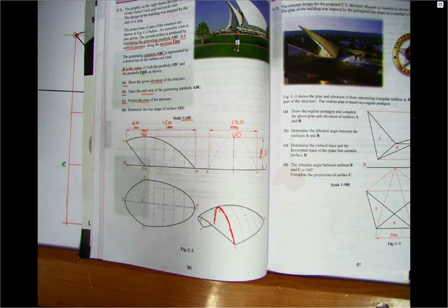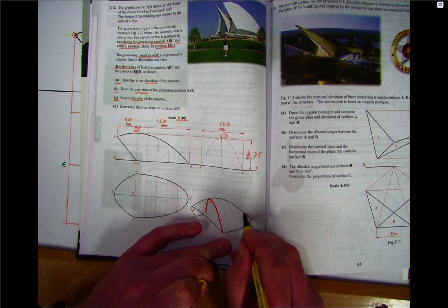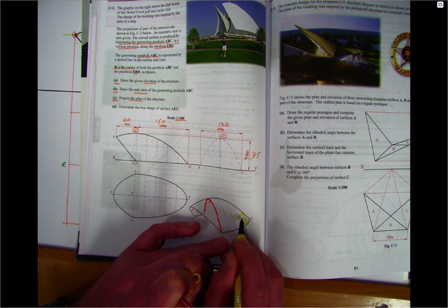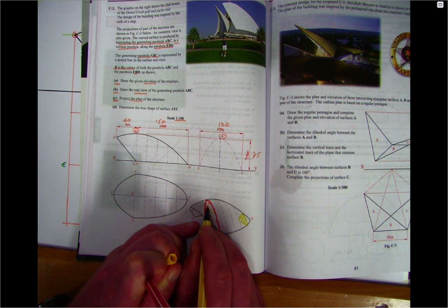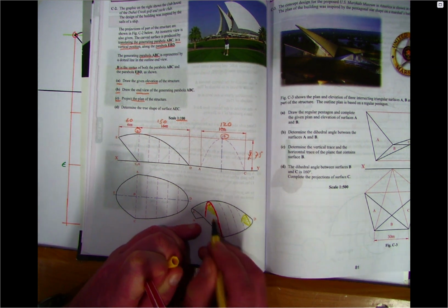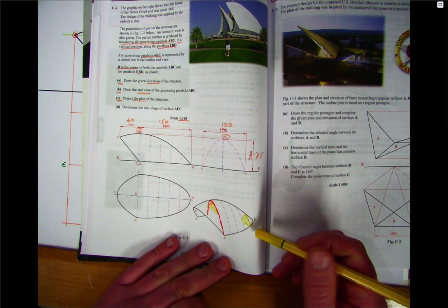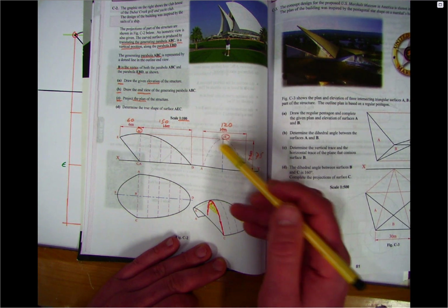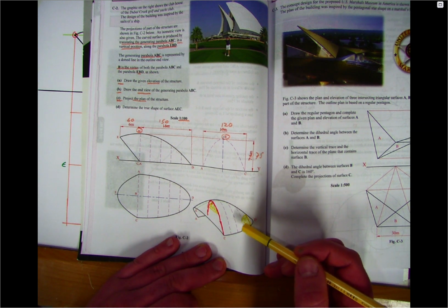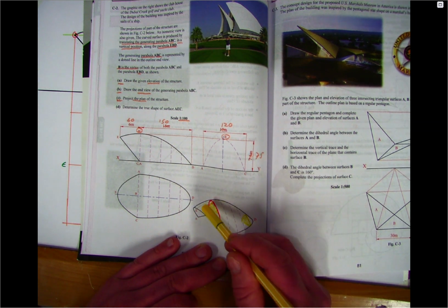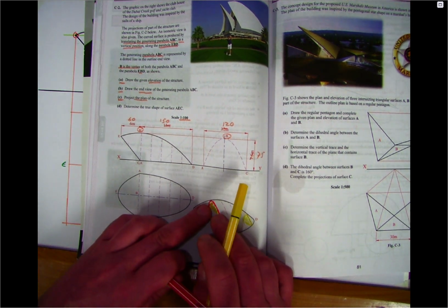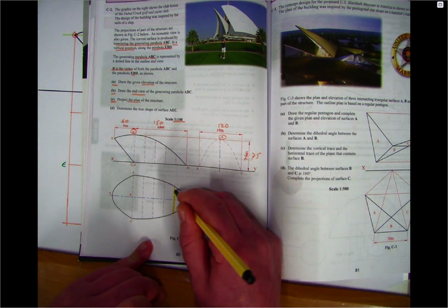So if I just take my yellow marker here, I just sketch in what the last one would be like. It'll be something like that. That portion would be the same here as this. So it'll be the exact same shape, but I wouldn't have used it all. Now, unfortunately, the construction of a parabola doesn't allow me to just find the width and then the height and then use the same method, my diagonals, to construct the parabola here, because it would make a slightly different shaped parabola. So what you actually have to do is use this parabola to solve how far apart this would be. If I could find that width here, I could find what that looks like in plan.